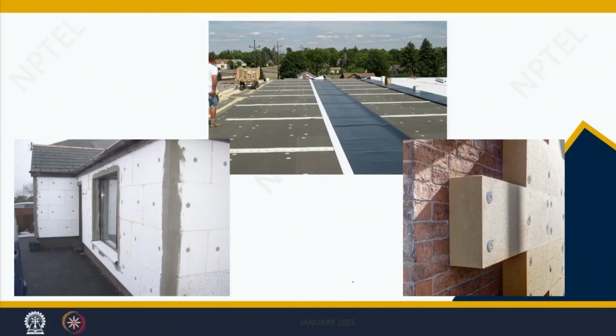You see, on a hot sunny day you probably cannot walk barefoot on the roof terrace, because its temperature is much higher, the solar air temperature is much higher. Maybe the temperature outside is 38, 39, 40, but you cannot walk on the terrace in the afternoon, maybe at 2 o'clock or so, because the surface temperature of the terrace is maybe around 55 degrees or so, 15 degrees higher, because of those parameters, with solar radiation very high, maybe 800 watt per meter square. That particular temperature has to be taken, and it will be killing you because of the heat transfer.